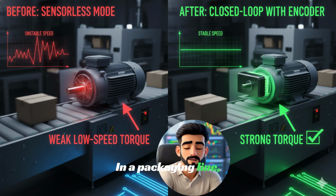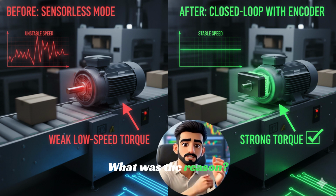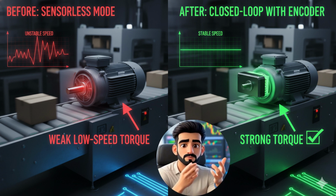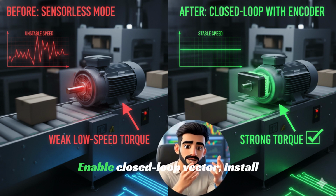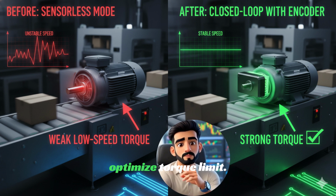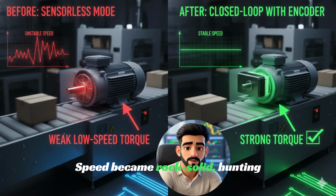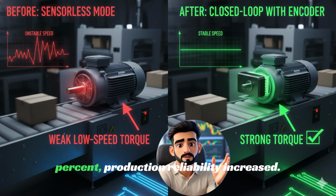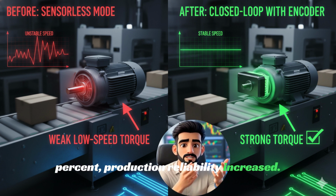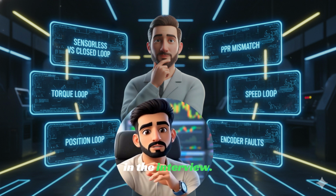In a packaging line, the motor speed was continuously hunting in sensorless mode. What was the reason? Low speed, sudden load variation, high precision requirement. What is the solution? Enable closed loop vector, install encoder, tune speed loop, optimize torque limit. What was the result? Speed became rock solid. Hunting stopped completely. Accuracy plus minus 0.1%. Production reliability increased. If you understand closed loop vector, then you are unbeatable in the interview.